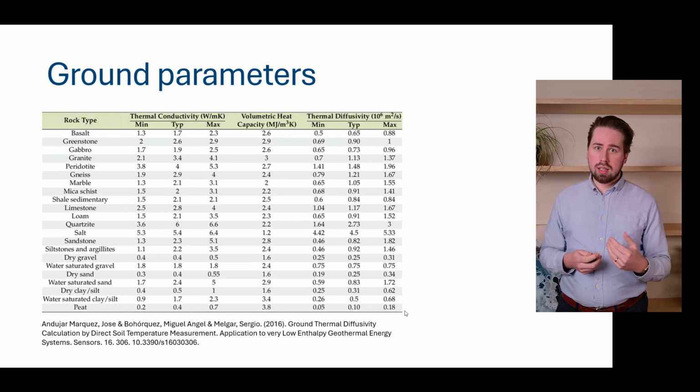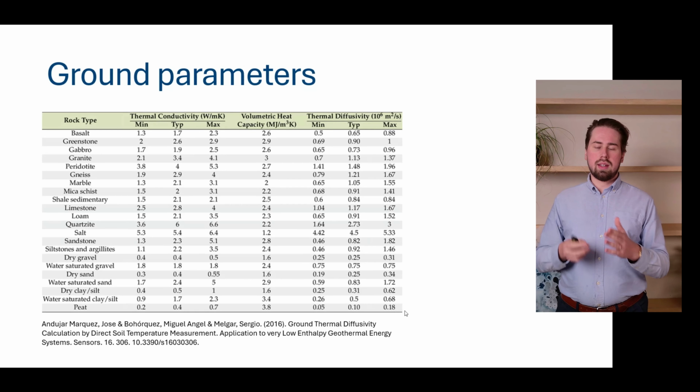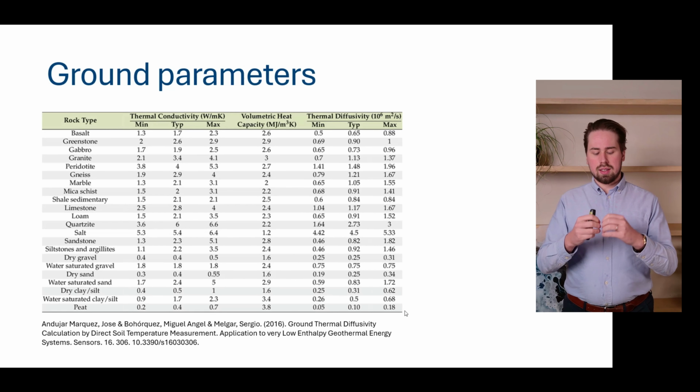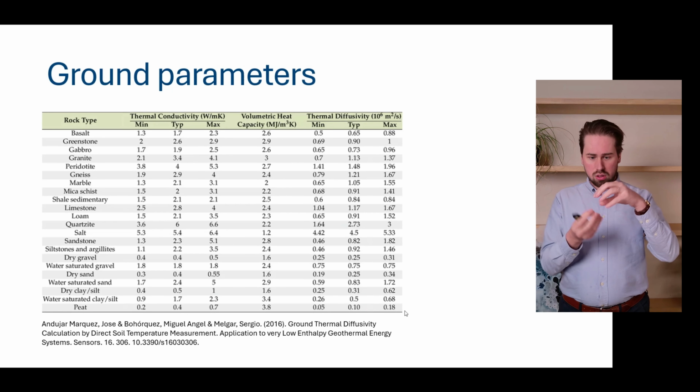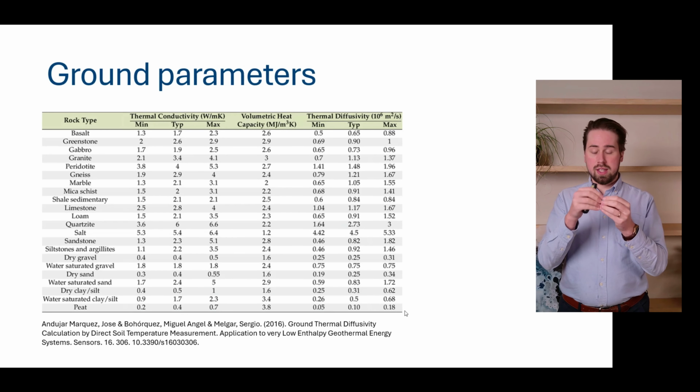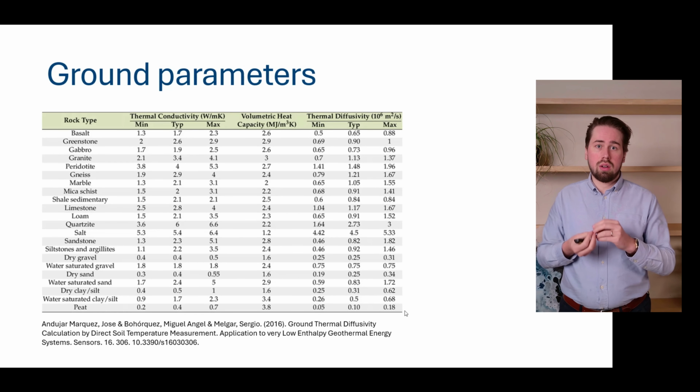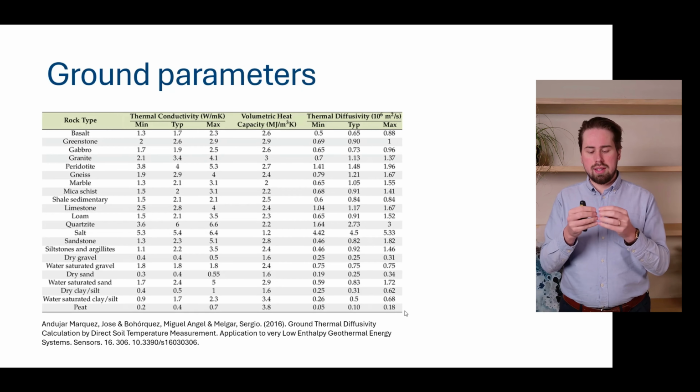When we look at the granular material, sands or clay and so forth, we see that there is also an important aspect of water content. You can see sand as small circles, small balls all touching each other, but it's porous, so there is either water in between, making it a good conductor of heat, also giving it a high volumetric heat capacity.